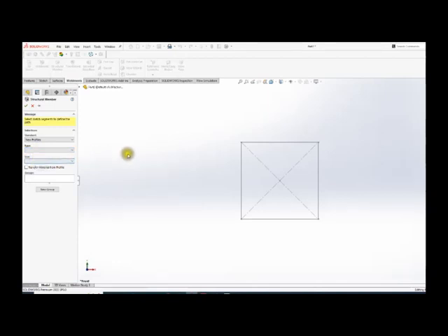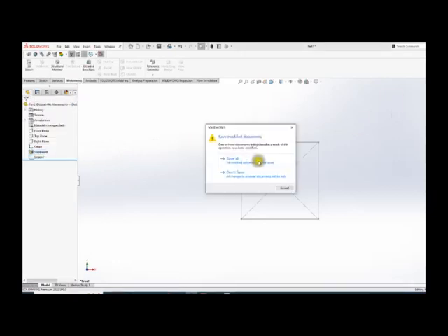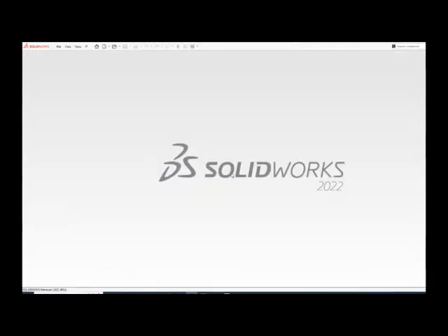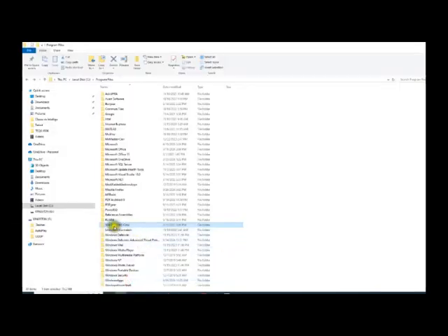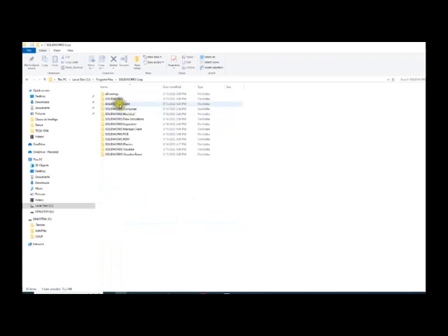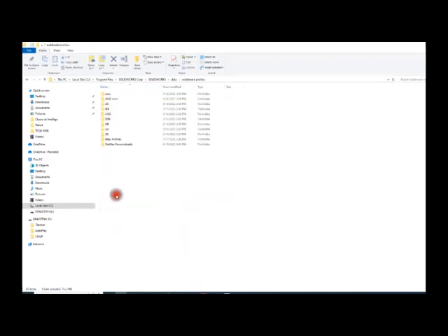Good. So again, we are out of here, and I don't want to save anything of this. It's just don't save. You have to go back to clean everything, so you gotta go back to your folder and fix that little issue there. So you gotta go back to SolidWorks, data, Weldment profiles, new profiles, and here's the issue.